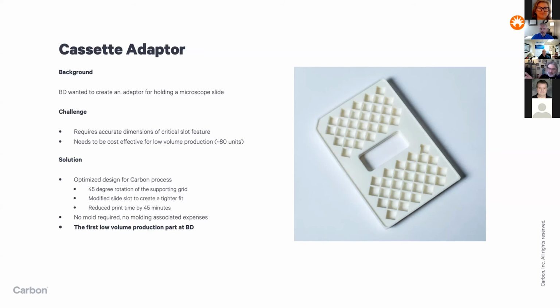And then they said, yeah, that shouldn't be a problem. Why would you want to do that? Well, now we've made it self-supporting. By doing so, we've taken off about 11% of the cost per part due to not wasted material and hand labor for the final part. So asking those simple questions can really lead to better outcomes just in economics to modify for printability.